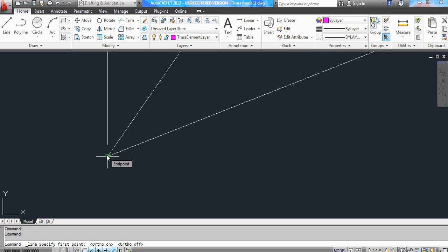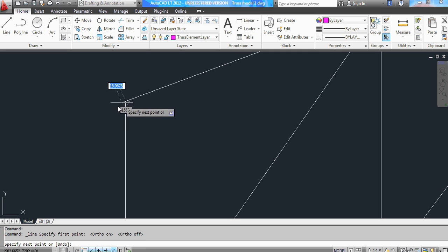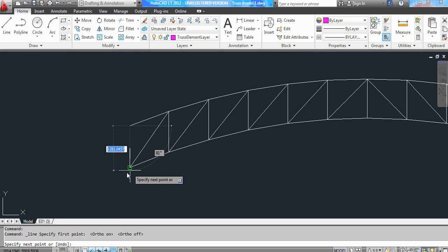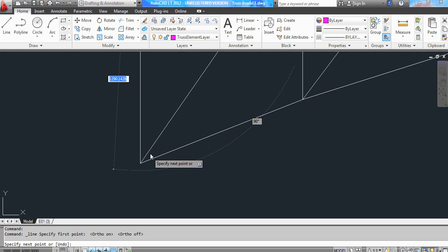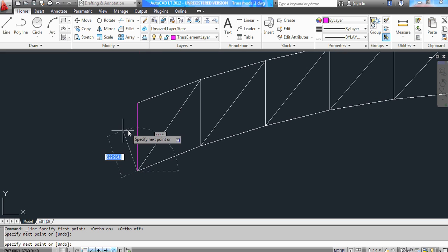Because in that one you create your coordinates and all the rest, and everything is just perfect. But in this case, it is very, very important you make sure the points you are clicking all connect. So I can start from the top. I just pick the line object and click on the first point. If you can get a mouse that has a wheel, it will go a long way, because you can always wheel to zoom in very well on the object you are connecting.